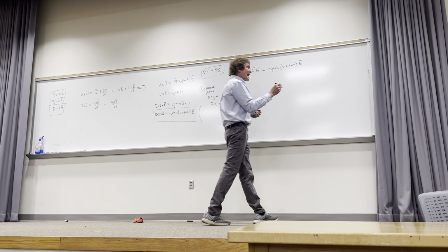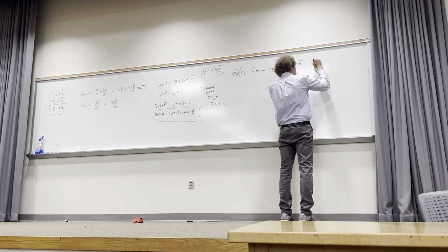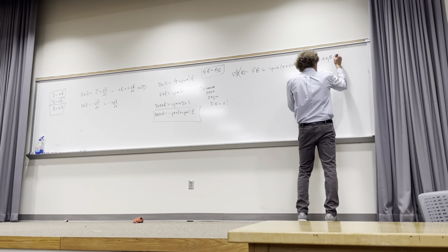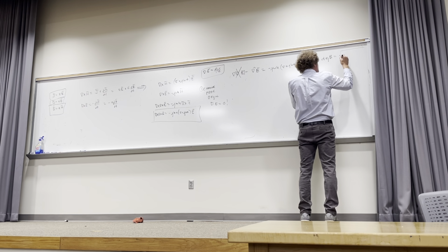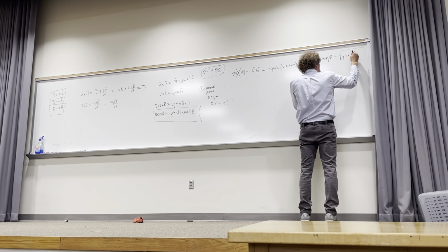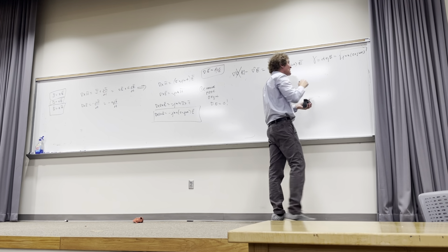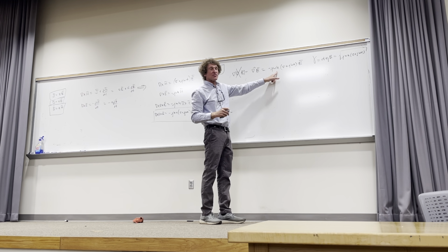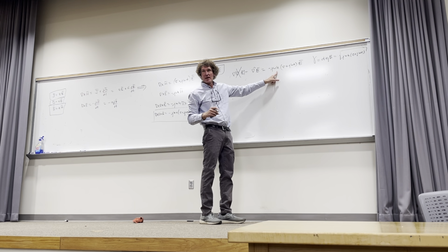We say that gamma is called the propagation constant, and it's equal to some alpha plus j beta, and it's equal to the square root of j omega mu times sigma plus j omega epsilon. And so now I'm going to introduce that constant gamma instead of writing all that out. You all follow me?